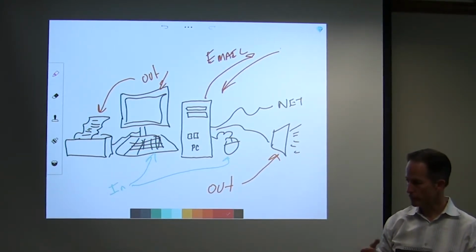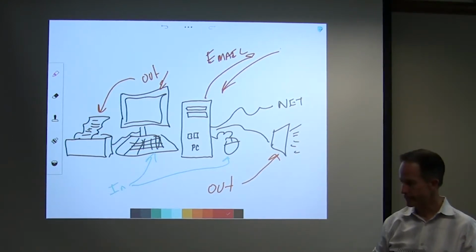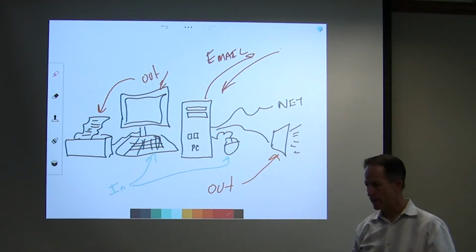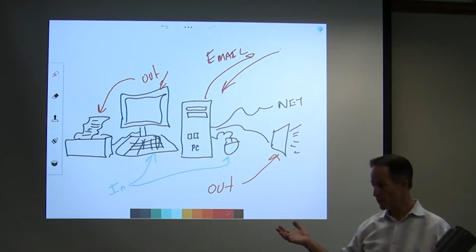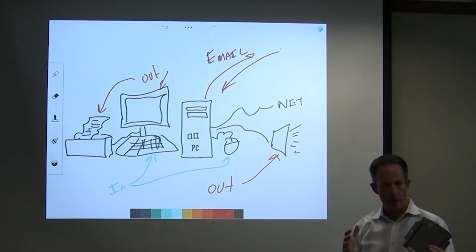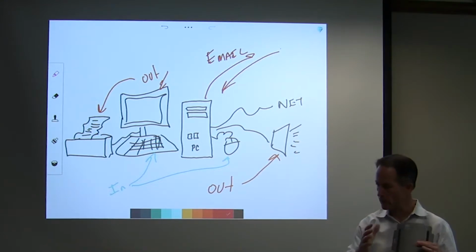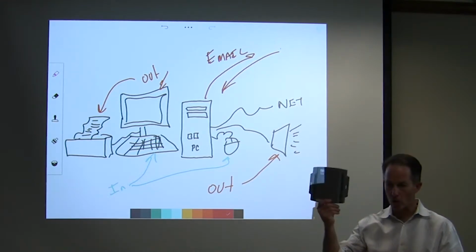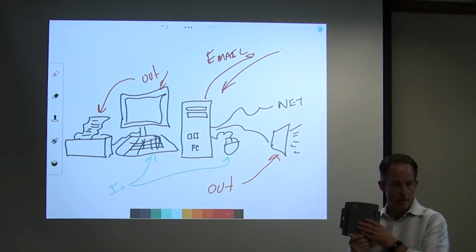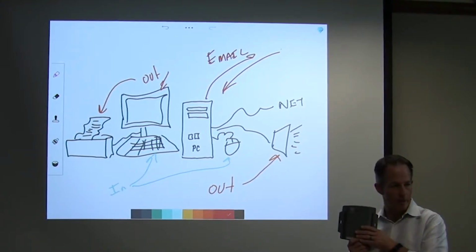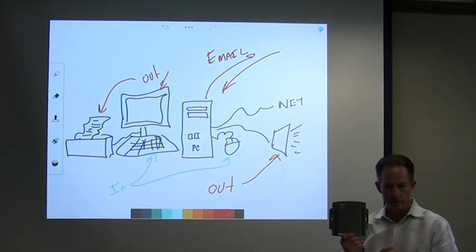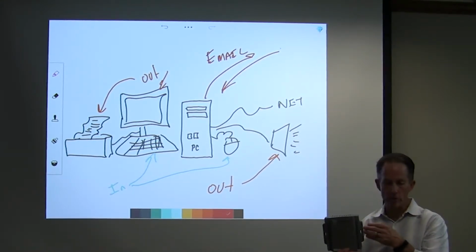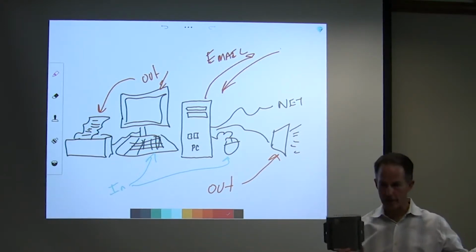Kind of how the outside air sensor controls a lot of how different air handlers react based on outside air temperature. Yeah, we broadcast that. Exactly. Outside air is one of the biggest ones we use. It's sent all over campus. We get a couple places, or one specific place, that we know is reliable, and then we share that across all of the other controllers. So for this controller, if it needs to know what the outside air is, is it a network variable input or an output getting something from our central plant? Yeah, network variable input comes into this controller. It then knows whether to open the damper or not based on the outside air, to do what it needed to do.